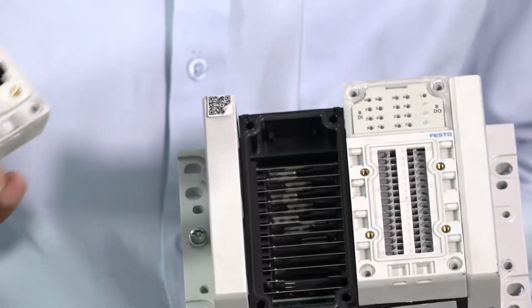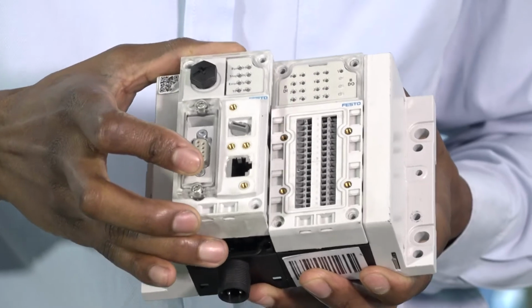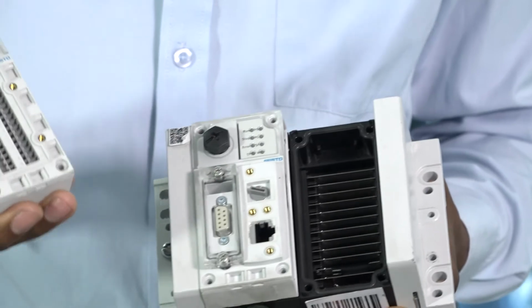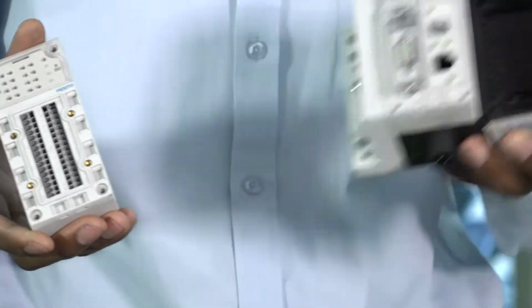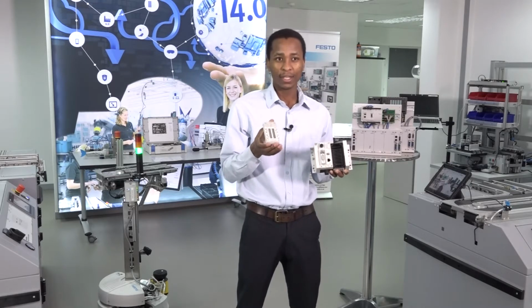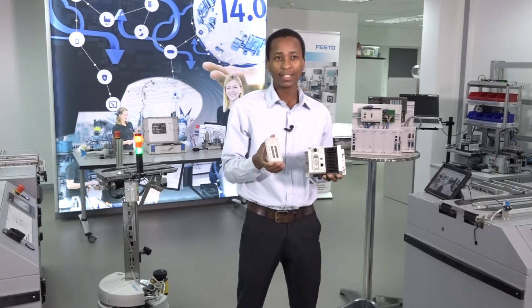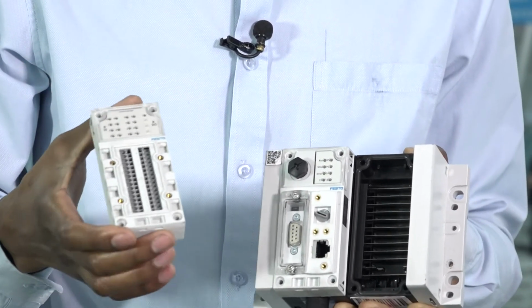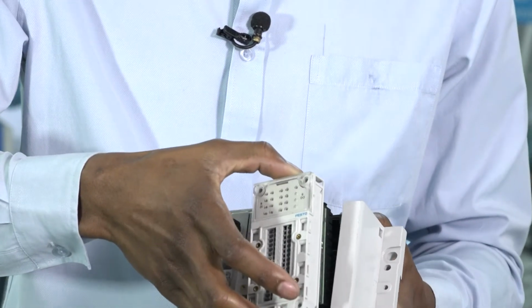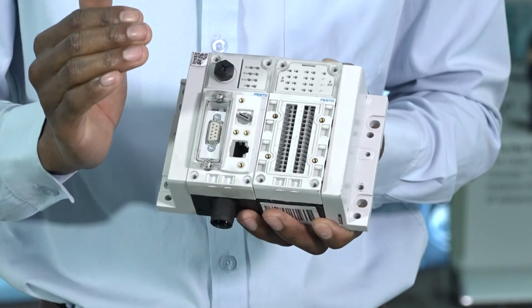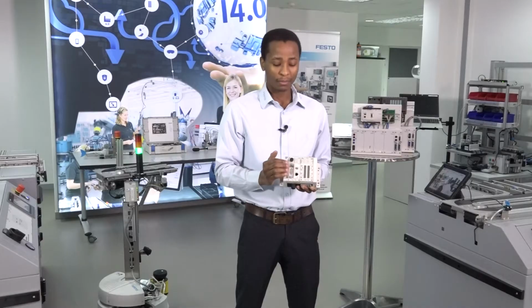So this is the actual CPU of the PLC. And we've also got here the IOs. When I say IOs, I'm talking about inputs and outputs. Now this will be the base and the CPU, and these are the IOs here. So this is an IO module. This can be digital, it can be analog. You can also opt for other field bus communication platforms, which I will go into depth in the future. So yes, you plug this in and then you write a code for the PLC. You obviously have to do the hardware configuration so that the CPU knows what is connected.